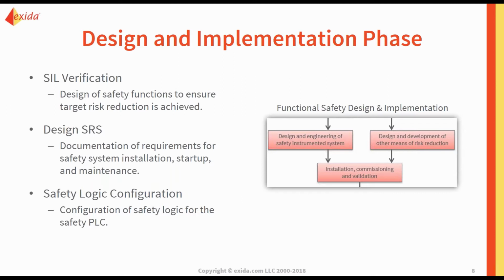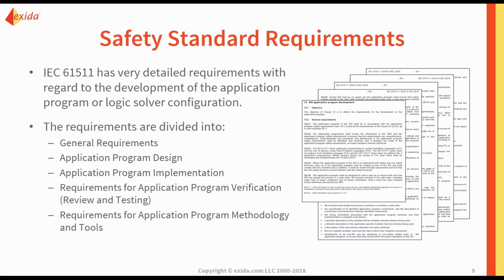The next step would be the configuration of your safety logic. So somebody has to interpret this information and configure the safety logic for your safety PLC. The standard has a lot to say as far as requirements go for your application programmer or logic solver configuration. So here you can see on the right-hand side, there is a lot of verbiage in the standard about these requirements, your SIS application program development. And I'm not going to go through all of it, but you can see it's rather extensive.